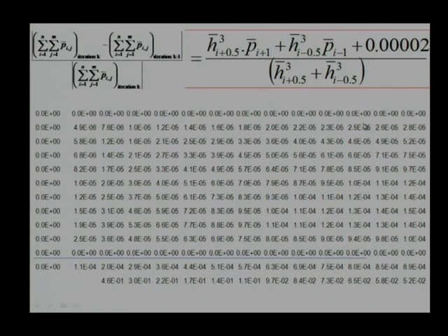After doing a number of iterations, say we count 13-14 iterations, we are getting this convergence value as 0.05. That means this is 5%. We started with the first iteration at 46%, and after 10-12 iterations it has reached 5%. That means the improvement is significant. We continue it if we have time, and we understand how the pressure profile is changing.